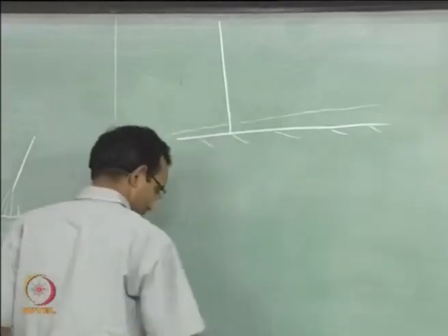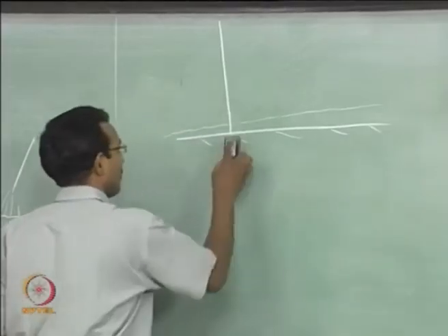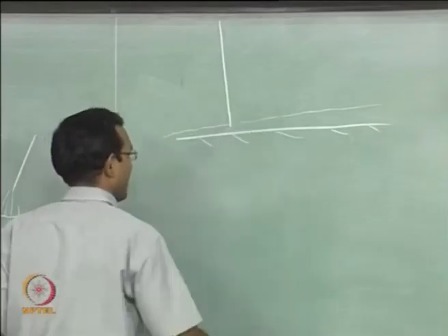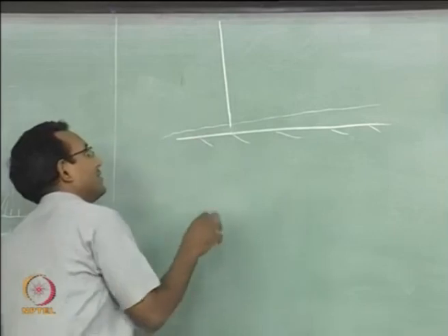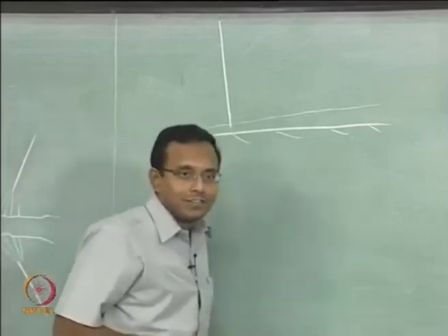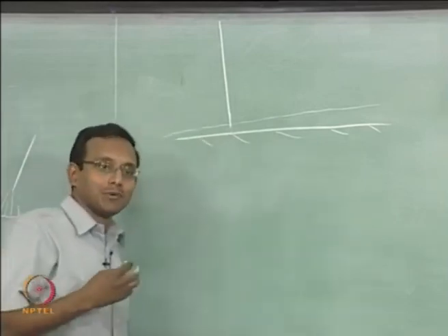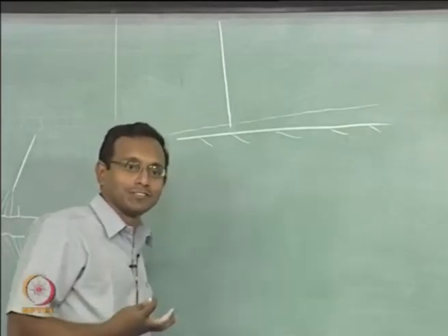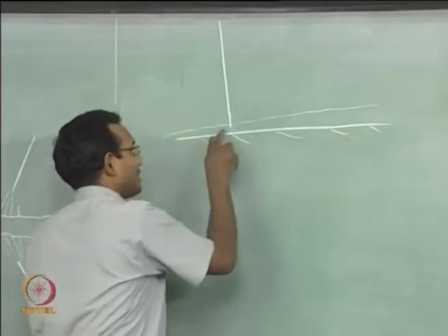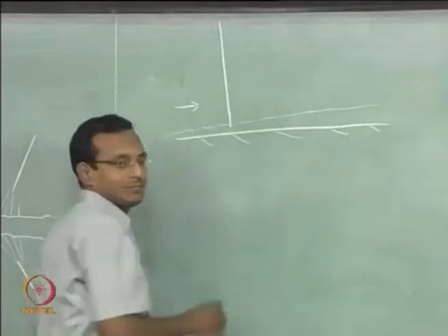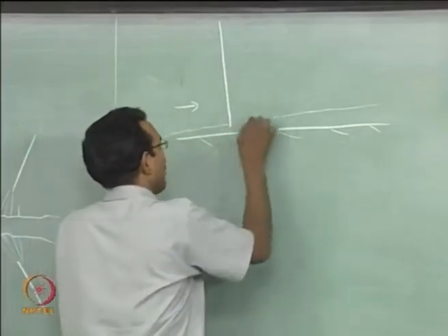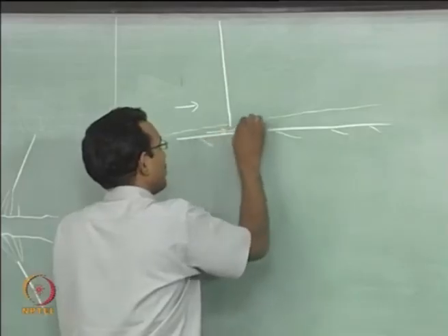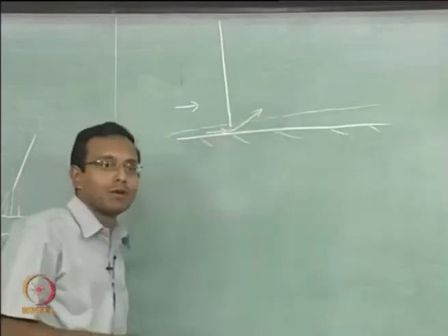But if it is a viscous flow, there will be a region where there cannot be a shock because it is subsonic flow inside. When the shock is coming and sitting here, you have to know more about boundary layers. I am just going to give you some information from boundary layer course. When there is pressure increasing along the flow direction, the boundary layer will suddenly separate from the wall and the flow inside will just want to go up away from the wall.